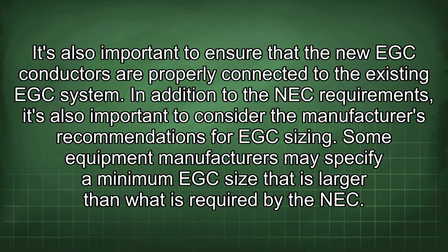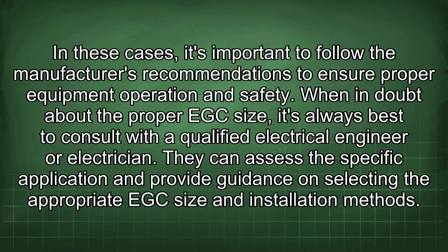In addition to the NEC requirements, it's also important to consider the manufacturer's recommendations for EGC sizing. Some equipment manufacturers may specify a minimum EGC size that is larger than what is required by the NEC. In these cases, it's important to follow the manufacturer's recommendations to ensure proper equipment operation and safety.